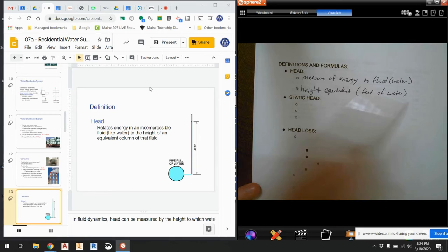All right, so again, the concept is imagine you're in a pool and you dive down 2 feet. The amount of pressure on your eardrums is the equivalent of 2 feet of head, right? There's 2 feet of water standing above your ear. And so if you converted that into a pressure in PSI, you could do that. Oftentimes this is referred to as a head.